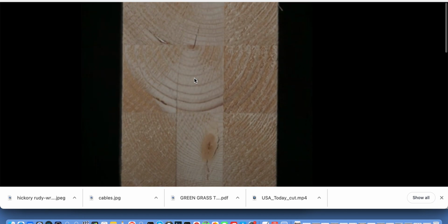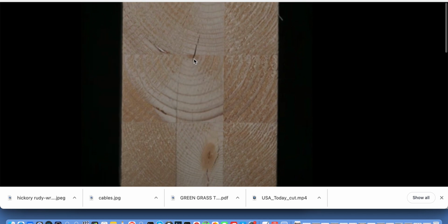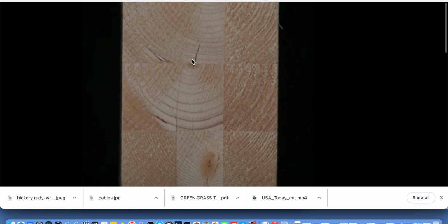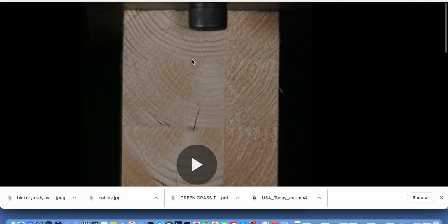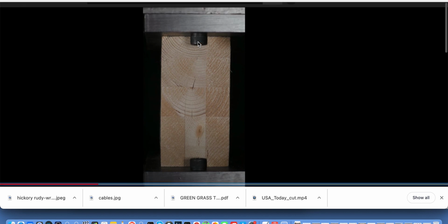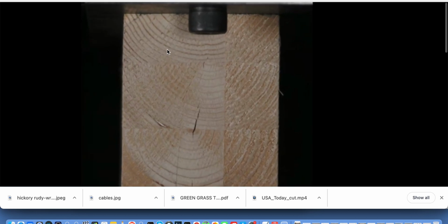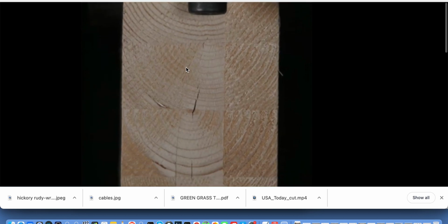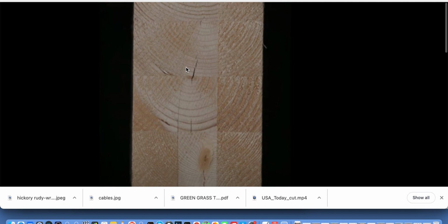Let's follow it. There's another knot. Remember the knot? So it jumped from here to here. The stirrups held, but there are no stirrups at the very knot itself, so it wants to fail at the very knots. Now this is just compressing the fibers together, and they have to displace, so they're starting to buckle out. But remember, the stirrups will want to hold as this compression is happening.